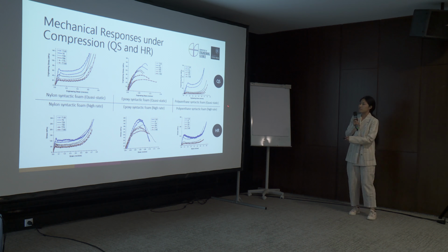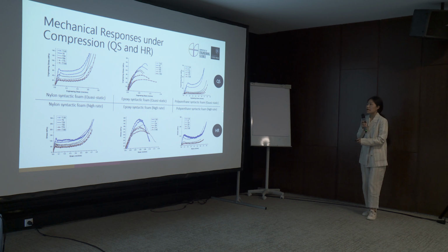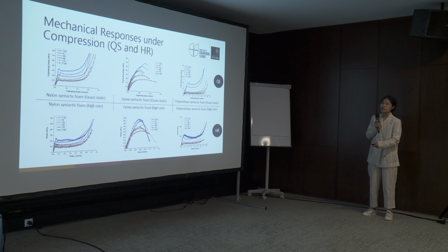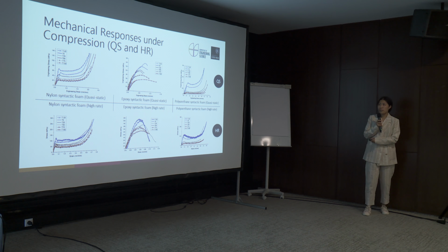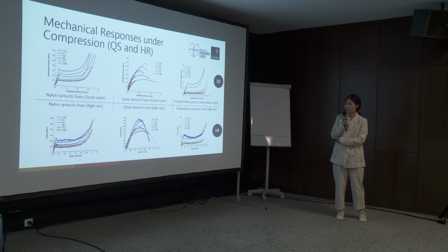It can be found that for the nylon and polyresin syntactic foams, their deformation corresponds to the classic compressive deformation of elastic-plastic cellular solids, which consists of 3 stages: the linear elastic stage, the plateau stage, and the densification stage. While the epoxy syntactic foam breaks in a brittle manner,